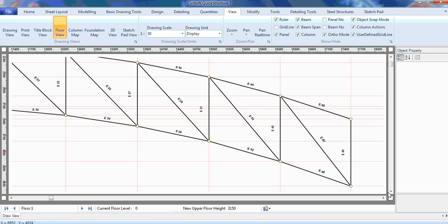Of course, as I said, you have to turn the drawing into a DXF for you to be able to read it in our design environment. You don't read in DWG, you must save as a DXF. Most CAD applications have the power to save as a DXF, so you must save as a DXF first before you can read it in.